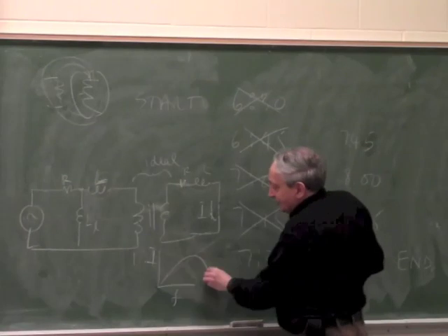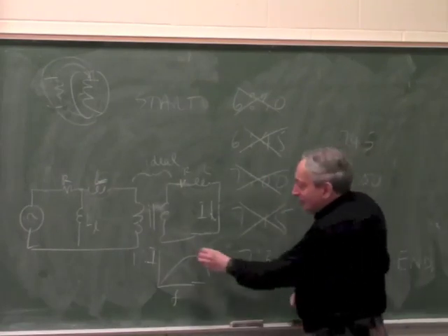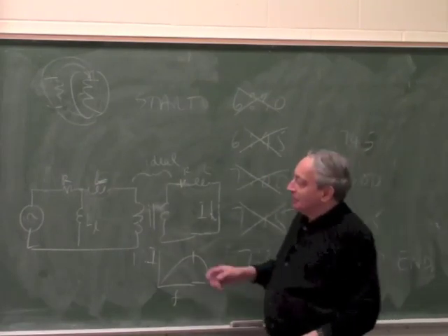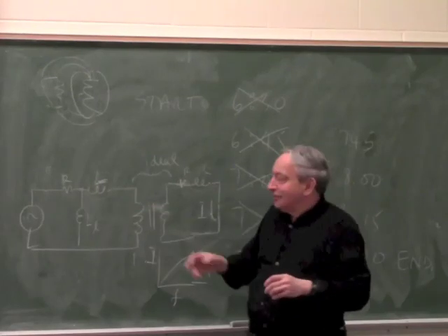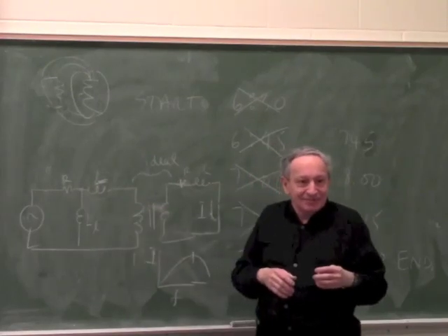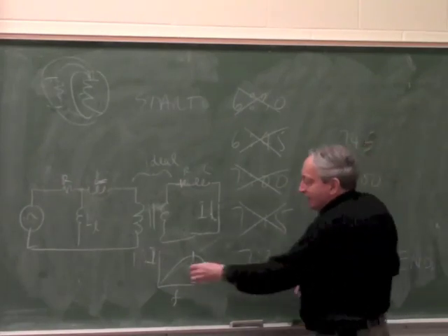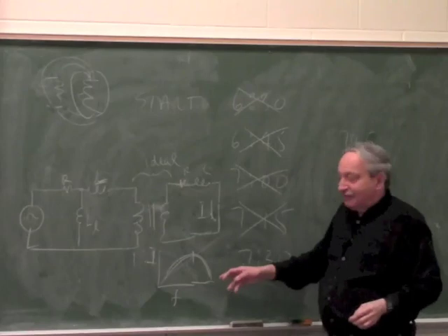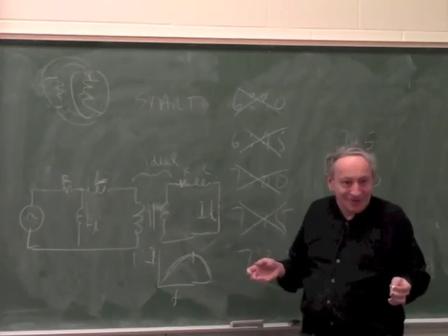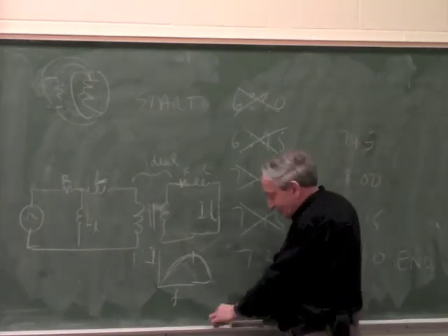It actually looks like this or something. So you can optimize this point by playing around with how much copper, how much iron, how much resistance, and so on. Because every transformer, if you look at a wide enough frequency, looks like this. Because at very high frequency, the transformer doesn't work. So optimize is where to put the maximum point.